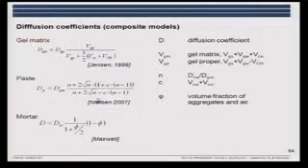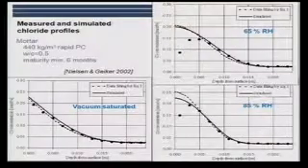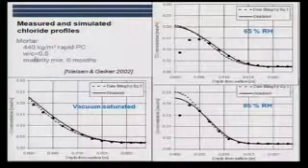We determined the amount of paste, in which are just composite models, and the amount of mortar depending on the amount of aggregates. Or the diffusion coefficient in the gel, in the paste, and in the mortar. And we were working with mortar. We made some samples to see the impact of the degree of saturation on the diffusion coefficients. When we did that, we used here the composition of the mortar: rapid hardening Portland cement, water cement ratio 0.5, and a maturity of 6 months.